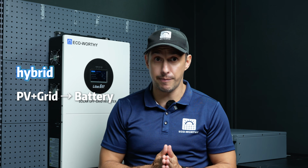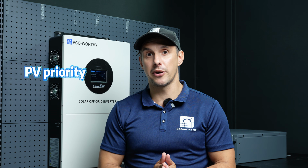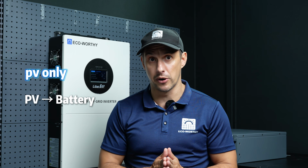Battery charge mode controls how the battery gets charged. Hybrid uses solar first and brings in grid power when needed. Mains priority uses the grid first. PV priority uses solar first. And PV only charges the battery from solar only.